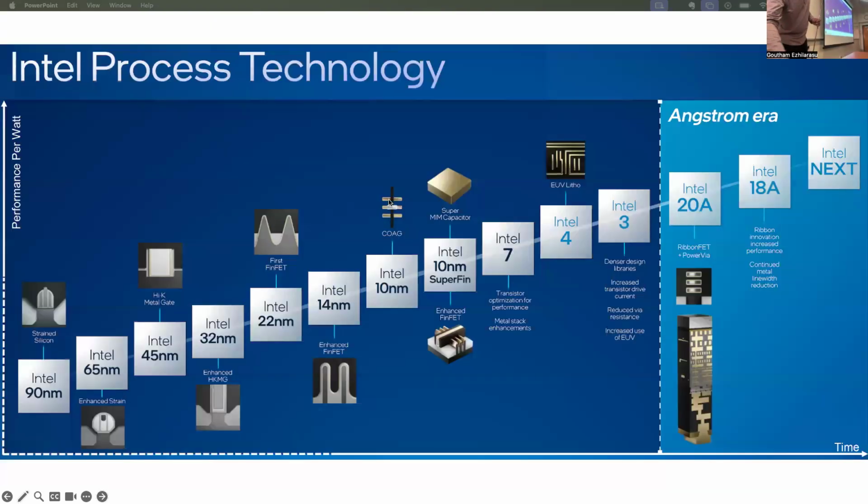So I think some of the things about Moore's law. You started with this kind of bulk MOS where you have a gate region, sidewall spacer, and source drain. But then, as the technology advances, when you hit 45 nanometer, you no longer can use a poly gate. You had to go to a metal gate, basically a high-K with a metal gate. And in order to do that, you need to do something called replacement gate. So you first create the poly and sidewall spacer in the original case. But in this case, in the final step, you remove that poly and then you replace it with a high-K dielectric as well as a metal. And then you do a polish step to fill in the gate region.